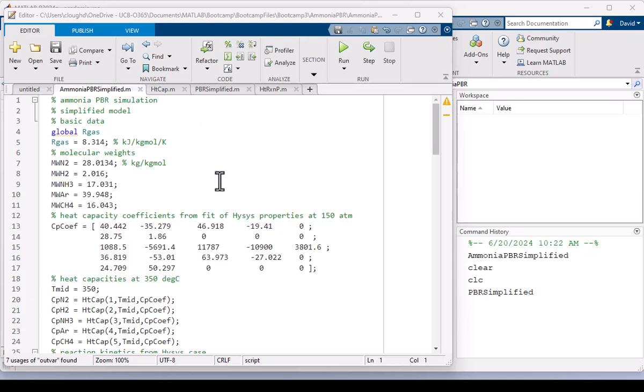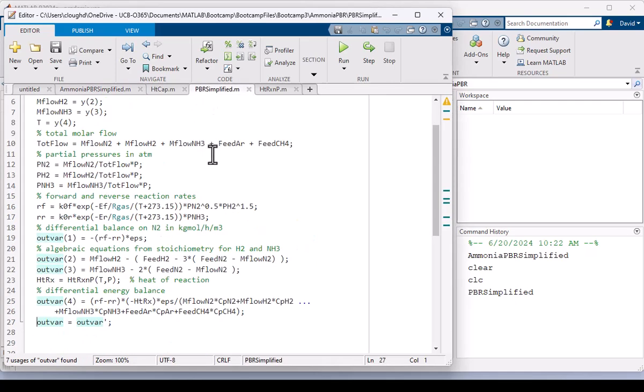Okay, what we're going to do here is illustrate a typical way to debug a model like this if you're having results which are incorrect as you first try to run it. So I'm going to come over to the routine that computes the derivatives and algebraic expressions. I'm coming down to the last line, and I'm going to click on the line number, and that creates a breakpoint.